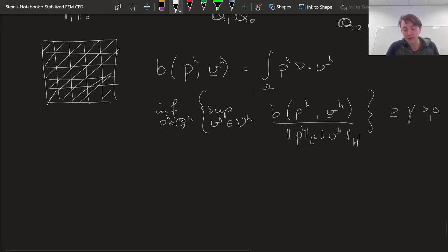So let's try and perform this operation, and let's specifically try the upper part of this operation. So I'm going to evaluate B(p, v) on this square domain with these elements. Now, that's not quite so difficult as it may sound. It's something that we can write out relatively easily. So first of all, we're going to subdivide this domain omega into all the element domains.